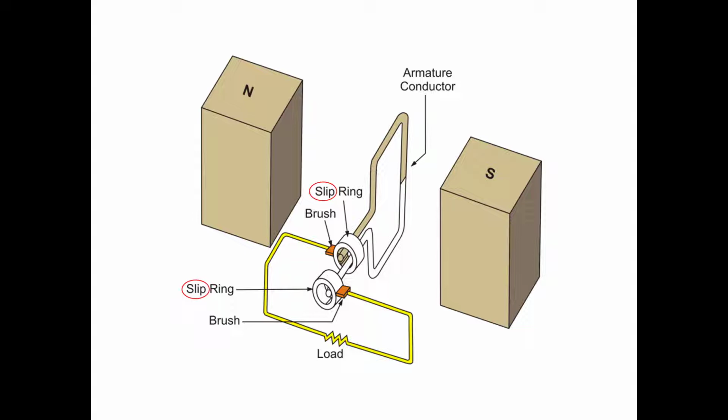Again, as they do here, we'll tie this onto a sine wave as well. So at 0, where it's sitting right now, it's not cutting any lines, so it's not generating any force. It's not inducing any EMF. Once we start rotating, we start cutting the lines. And then at 90 is where we get our maximum generation. We'll revisit that when we come through.